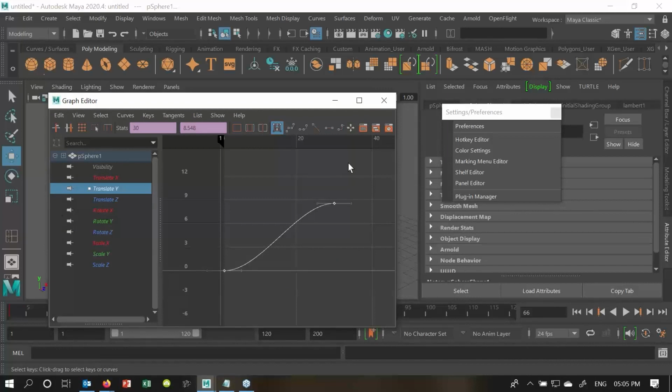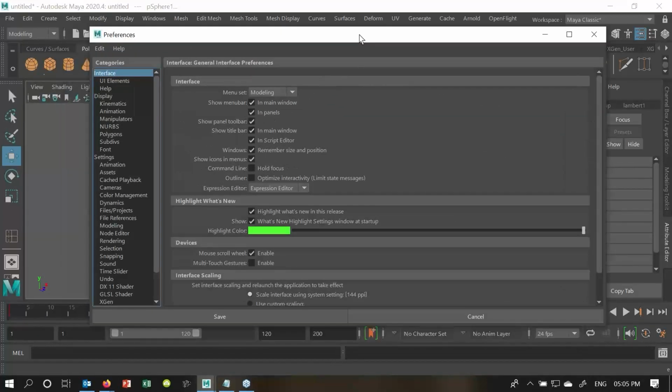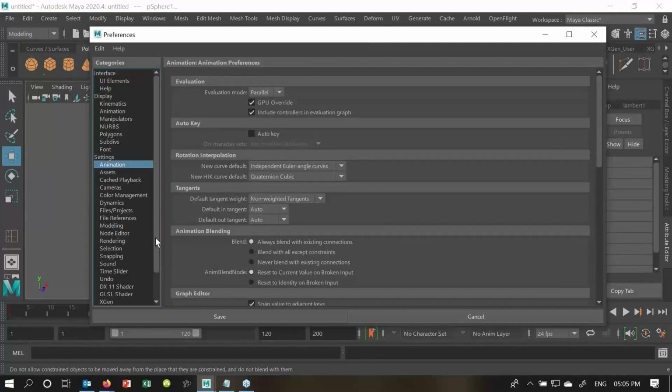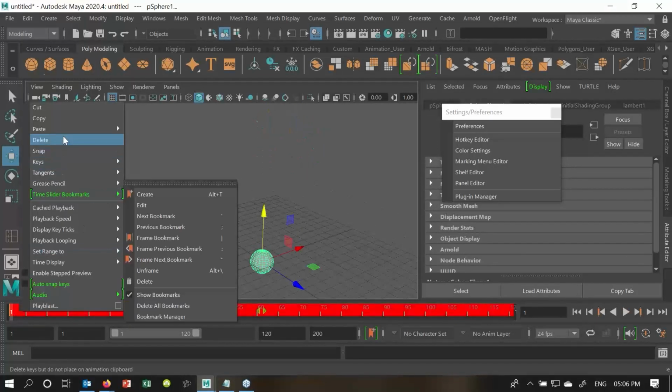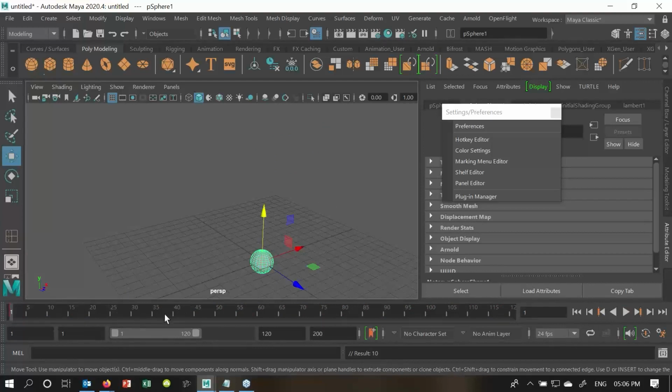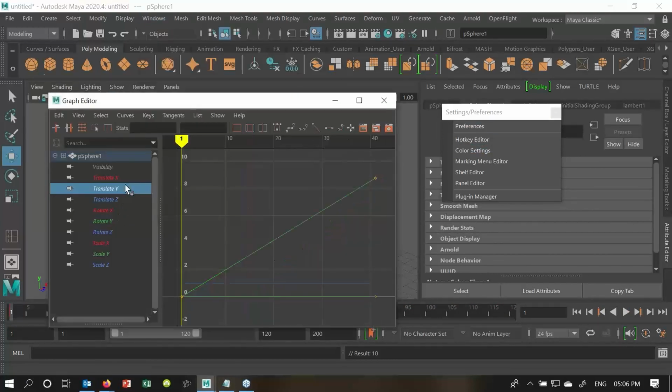If any students want to become an animator, auto is the option we have, right? So it's always preferable when you are doing animations that we use spline. So I do not want it, whenever I create keyframes, to always go into auto. Before that, we create the spline and save. Now if I animate this, it will come as a spline. Again, go to Window, Animation Editor. If it's not coming, we need to restart.